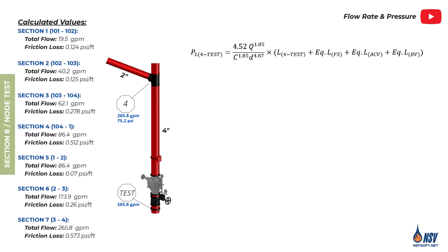Let's begin by calculating the major and minor losses in this final section. As we know, major loss refers to the friction loss that occurs along the length of the pipe. Minor loss, on the other hand, results from local disturbances and energy dissipation caused by components such as valves and fittings.